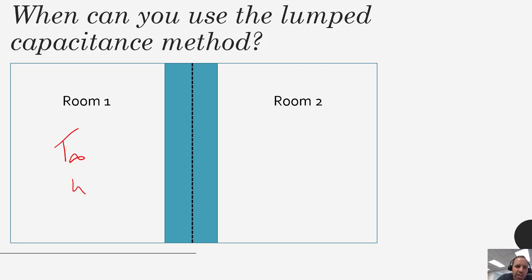So let's look at the temperature at the center of this thing. We're going to have a symmetrical system, so we can do this kind of thing. So let's think about the thermal resistance through the wall itself, and then the thermal resistance associated with convecting back out into the ambient air of the room.